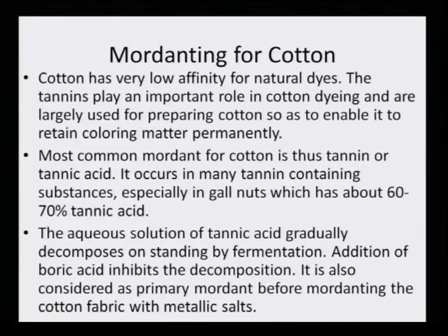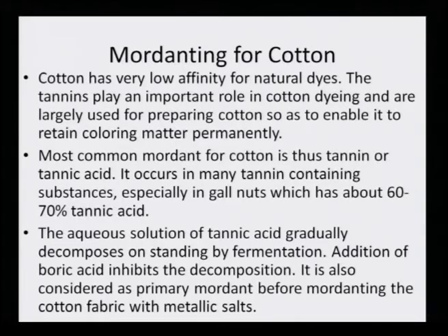Mordanting of cotton, because cotton is the most tough to dye, and therefore, again and again I am mentioning this because I want you to understand and appreciate that cotton dyeing is the toughest, and so many measures have to be taken. A tannic acid pre-treatment, a mordant pre-mordanting or post-mordanting or simultaneous mordanting is a must. Cotton has very low affinity for natural dyes. The tannins play an important role in cotton dyeing and are largely used for preparing cotton so as to enable it to retain color matter permanently. Most common mordant for cotton is thus tannin or tannic acid.